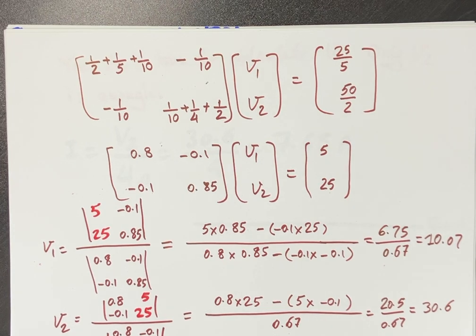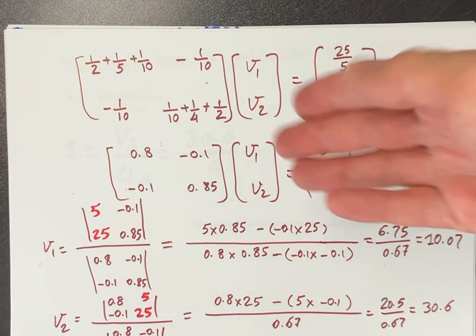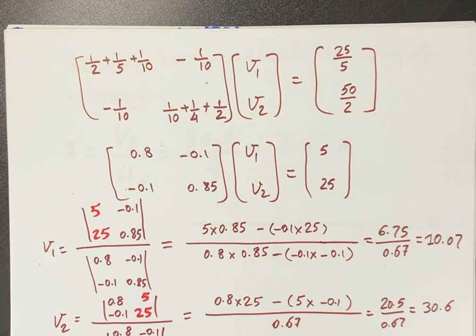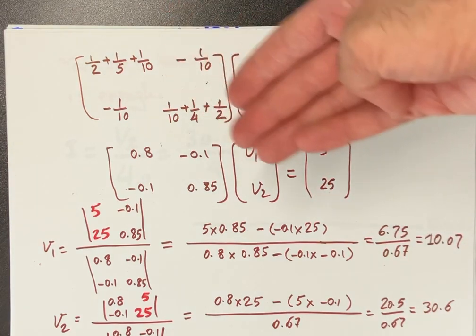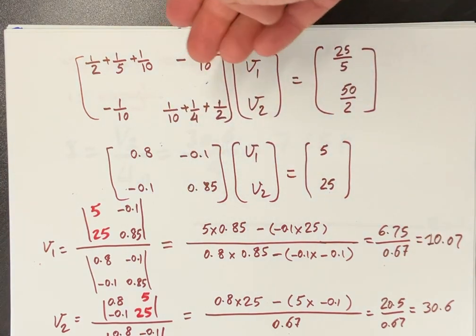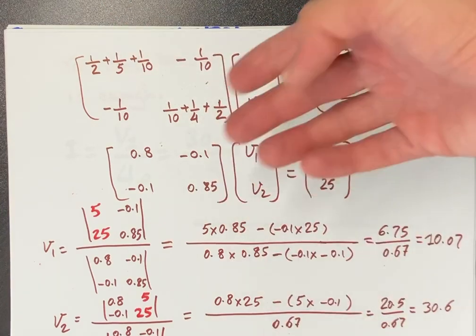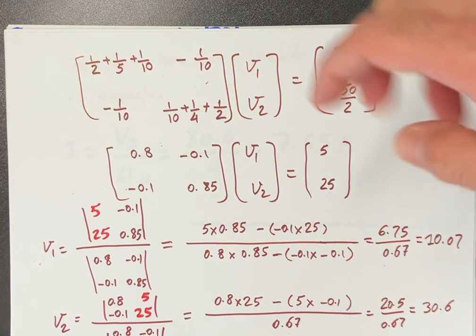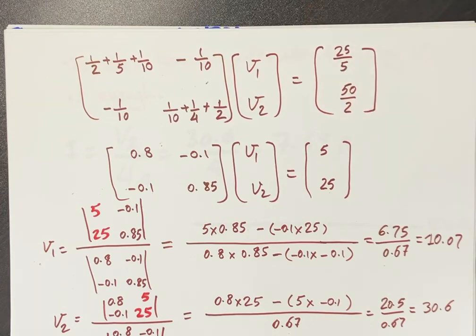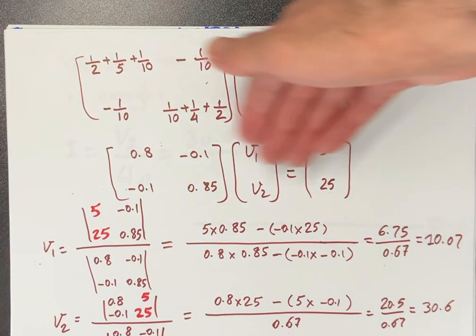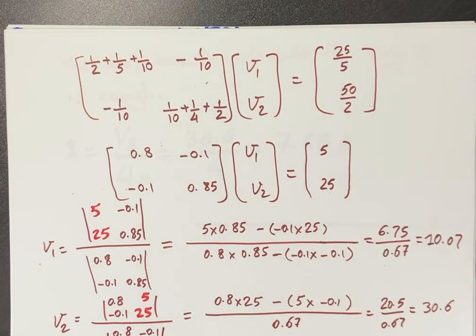Obviously, if you go for the nodal method, you get the answers faster because you need to deal with a 2 equation, 2 variable problem. One way is to start by writing KCL and then go to the matrix way or elimination method. The other way is generating these matrices quickly and then continuing with the rest of the calculation.